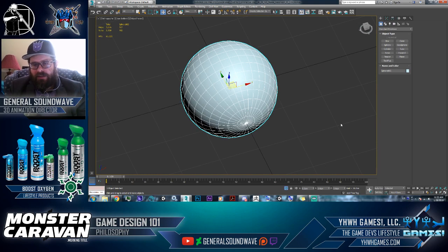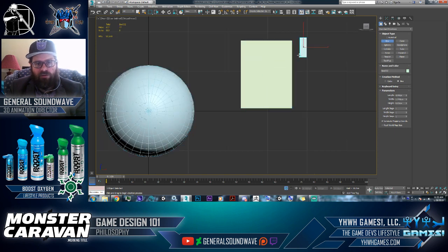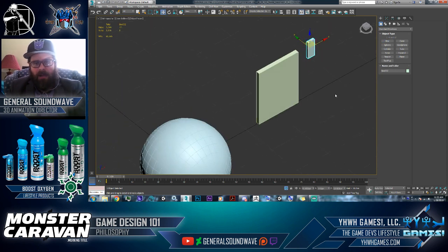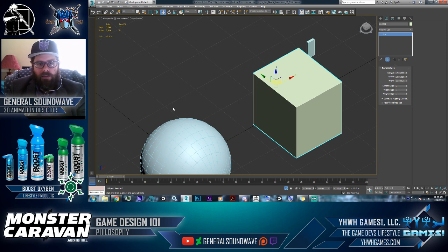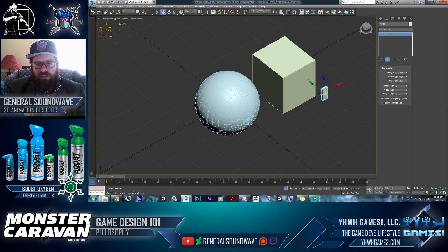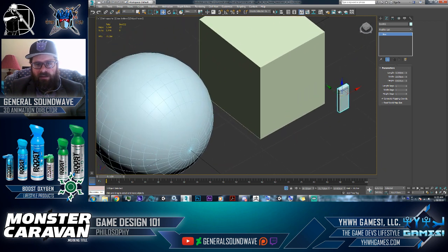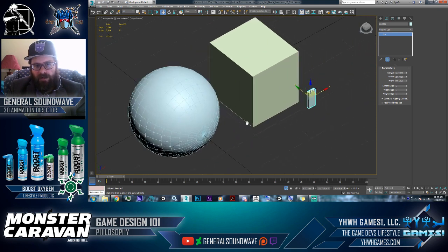Okay. Now the next thing that I would like to add, of course, the viewport toggle. Okay. So let's understand some things about the camera. This is all still part of navigation. So I'm going to go to the create panel real quick. I created some boxes. I'm also going to make sure that these have some depth to them. Okay, so let's go ahead and just place these over here. So right now I'm actually using the move tool. So now you can see that these 3 objects are locked in XYZ space. And I'm just moving my camera to get focused.